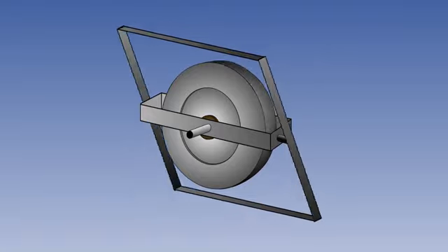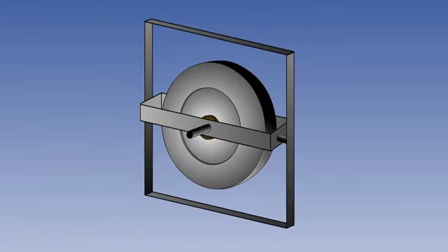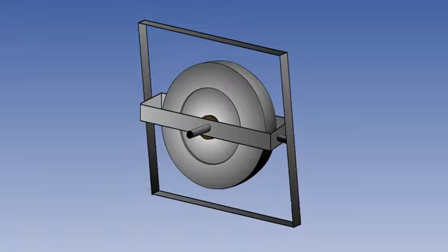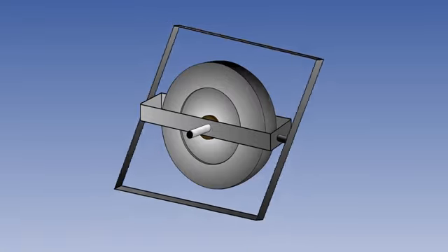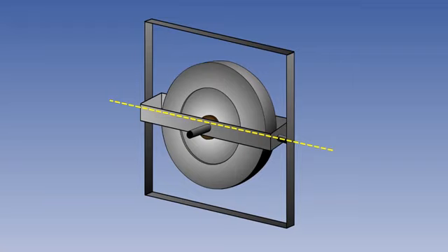The pivot point on the inner gimbal bears on a second or outer gimbal, and this gives the outer gimbal the freedom to rotate around the inner gimbal. The inner gimbal or single gimbal is therefore said to provide 1 degree of freedom. Finally, the outer gimbal is pivoted in a housing which is fixed to the aircraft.